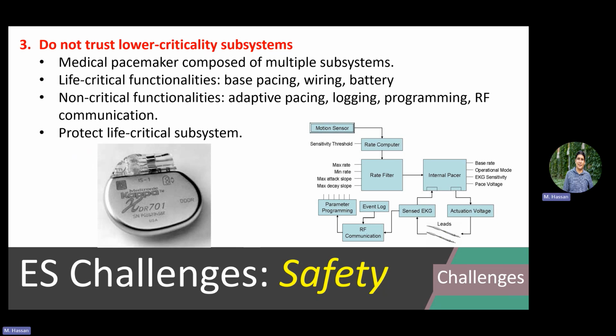Yeah. Then how do you trust any device that connects to the internet or Bluetooth in general if you can't keep them apart? Yeah, that's in fact one of the biggest problems in connected embedded systems, right? How can we really trust it if it's connected? One way is to develop tasks that are connected, that are completely isolated in hardware from the critical ones. They don't communicate anything through hardware.